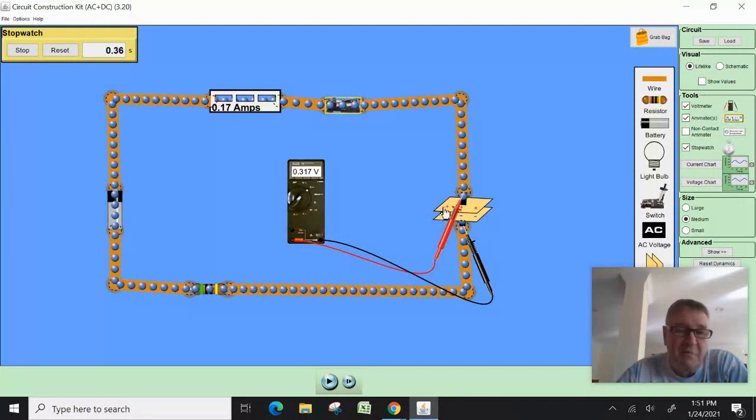It's going to try to do it until this becomes 9 volts. So we're definitely early on in the process of that charging curve. You'll also notice that the current has spiked. And when I run this for a long time, I want you to pay attention on both of these back and forth. You're going to see the current go down pretty rapidly, and the voltage go up pretty rapidly, at least initially. And then as this becomes closer and closer to 9, this process will slow down, and this will also slow down. So it'll go to 0, and this will get closer to 9. You can tell I ran this for less than half a second.